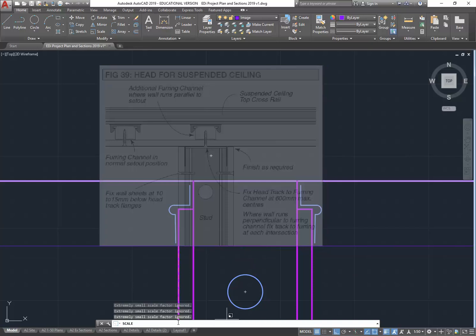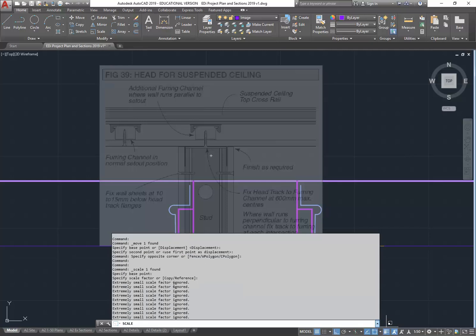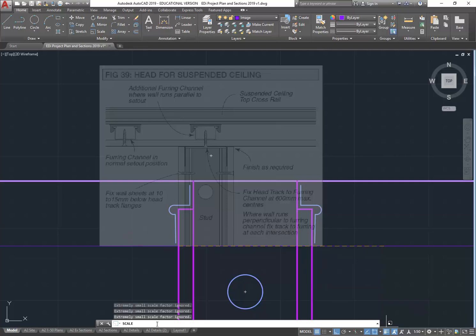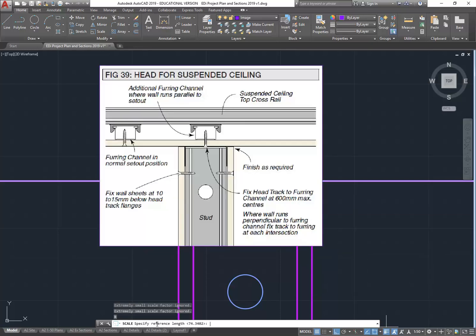It's not letting me see the options, but if I click on the up arrow there, I can see that it does have the copy and reference options. So the secret, if you want to get those options and you can't pick them from the menu, is you can still type the first letter, usually. It's the capitalised one technically, but generally the first letter, which is R, then enter, and it still works.